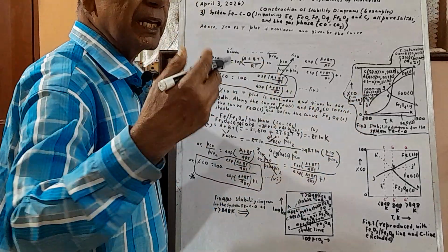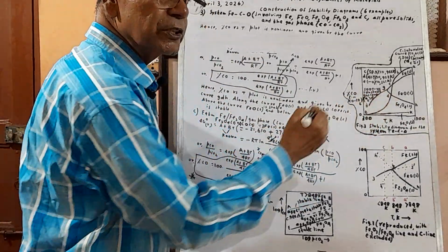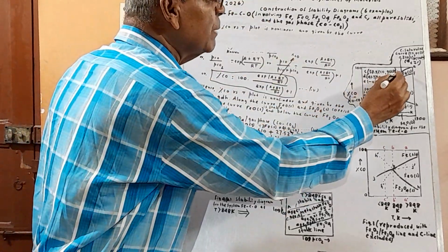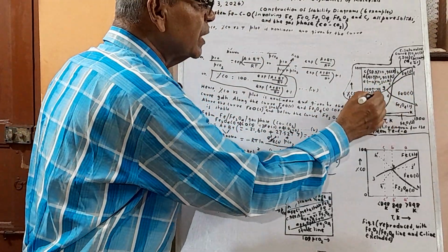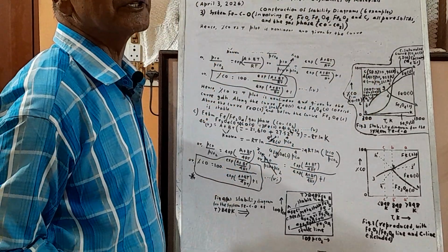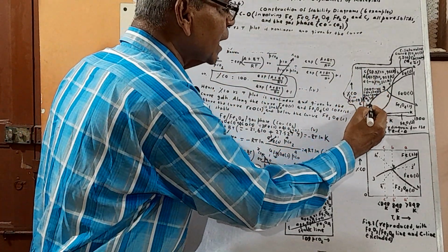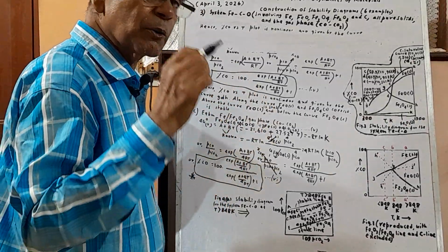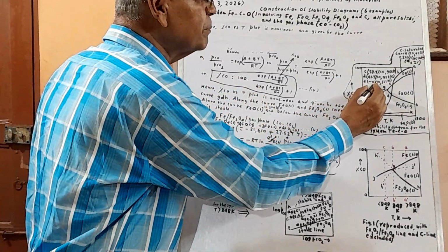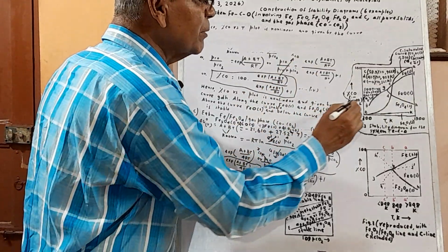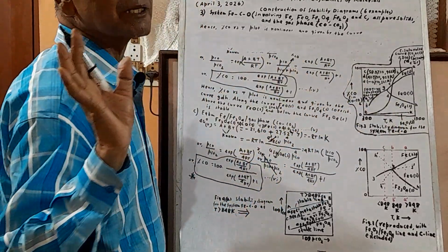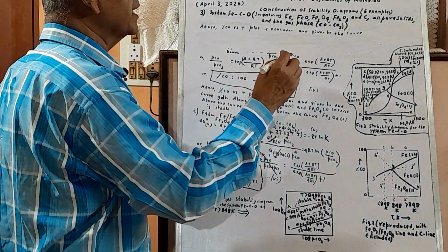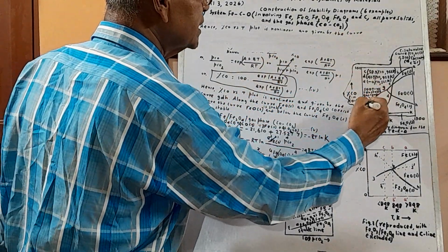I repeat then. This is Fe3O4. In rotation, FeO, Fe3O4, Fe. So this is along this curve GJ. Fe3O4 and Fe coexist. Above the curve, Fe is stable, and below the curve, Fe3O4 is stable, along with the gas phase. So this we are going to handle, given by the curve GJ.